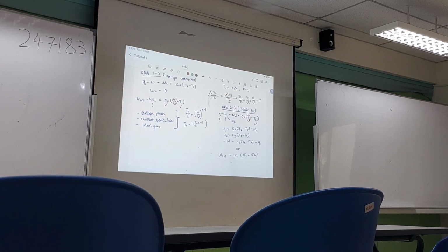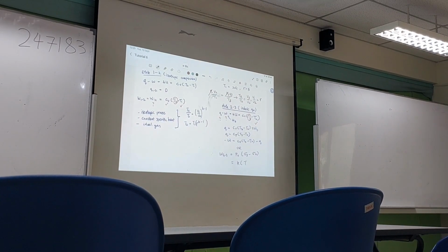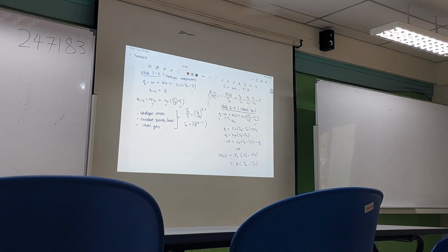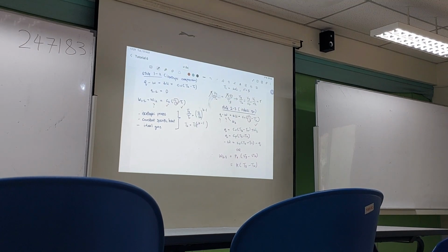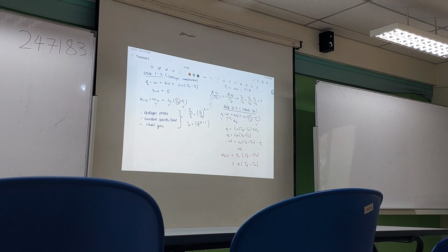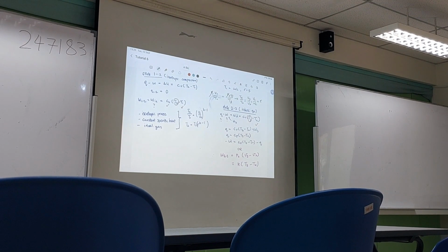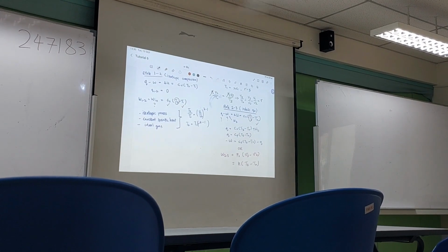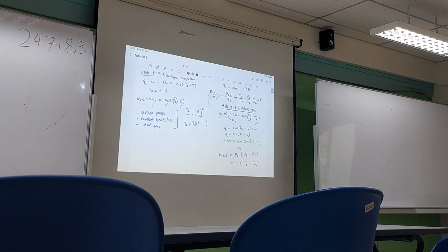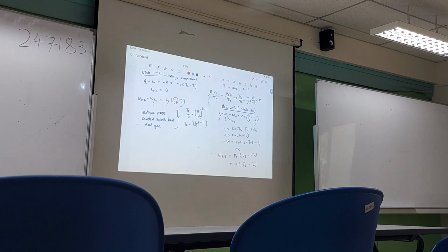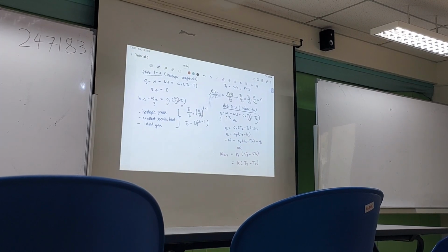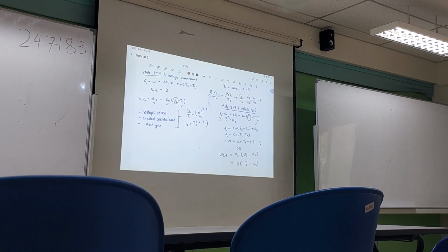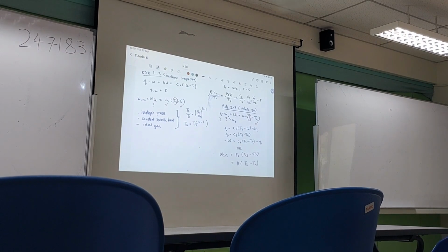And this is where the ideal gas law will come into play. So you can actually replace this with this, because they're the same thing. PV equals to RT, mRT. So then this way, you can get the boundary work. And then after that you can find Q. So actually, either way is fine. If you stick to the bottom method, then you actually don't need to find enthalpy.